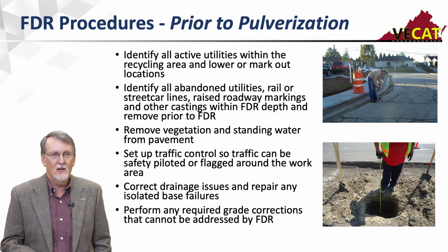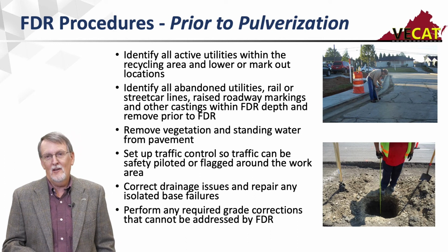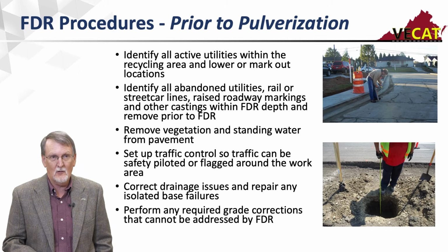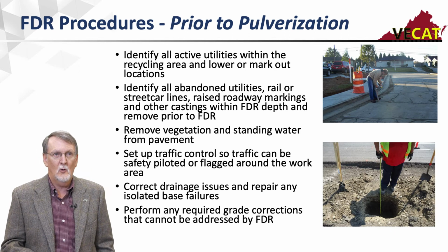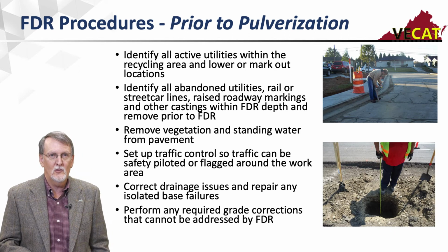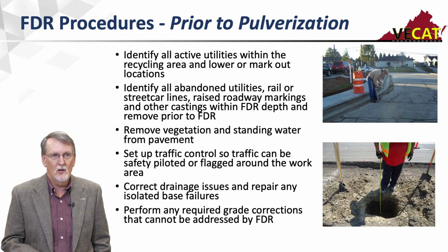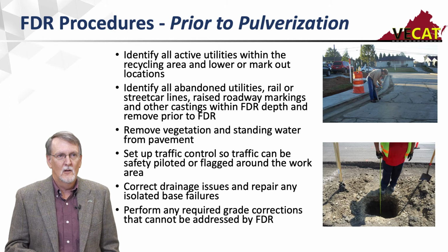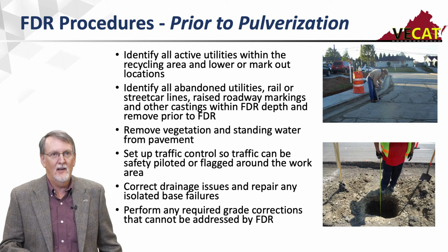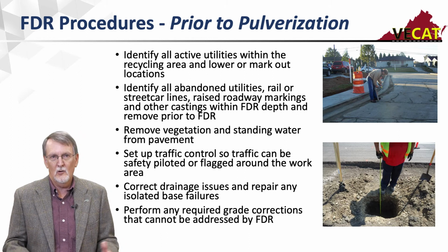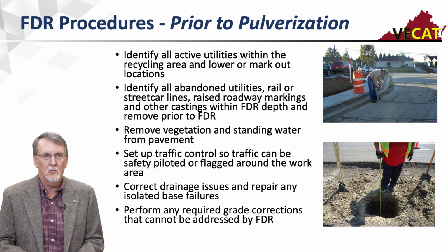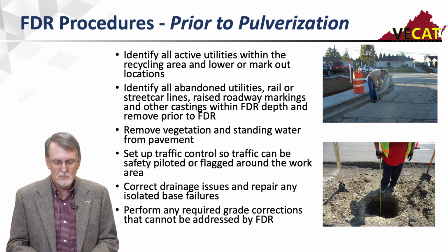Like any other project, I don't want vegetation and standing water from the edge of the pavement to get into this recycled mix. So I want to be sure I remove all that vegetation, sweep it clean. We're going to do this under traffic usually, so I want to set up my traffic control so it can be safely piloted or flagged around the work area. Again, that reclaimer is only about 8 foot wide, so there's generally plenty of room to work the traffic around it.